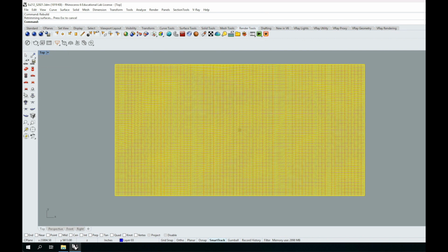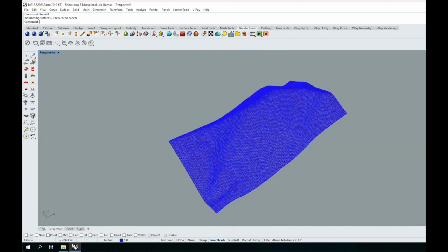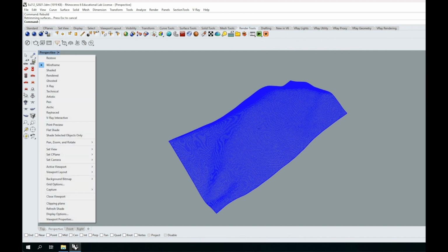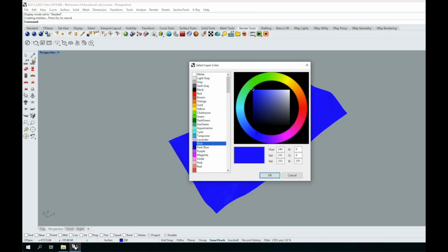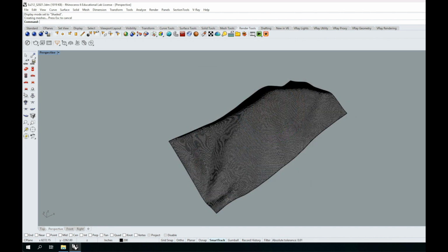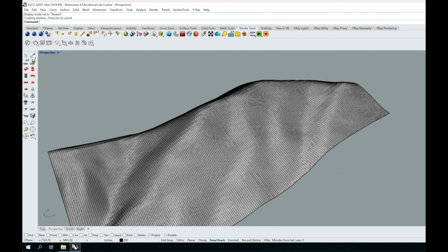And we will rename layer 3 here to be 200. So let me double click and type 200. And there we go. If I switch over into the perspective view, we can see that surface there, and we can turn off contour X and contour Y and see just the surface itself. I can also switch over into my shaded mode so I can see it a little bit better. The blue color isn't really working. Let's try black and see if it works better. Last time I picked white and I thought it worked pretty well, but actually black I think gives us a little more shadow. So we'll do that.